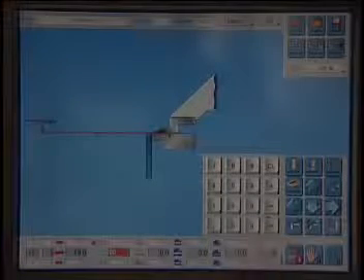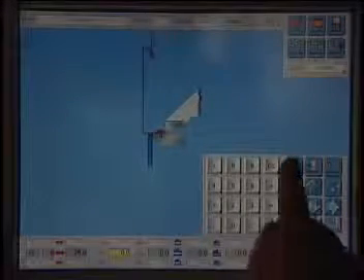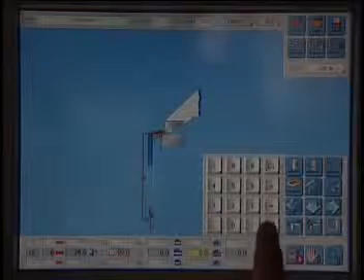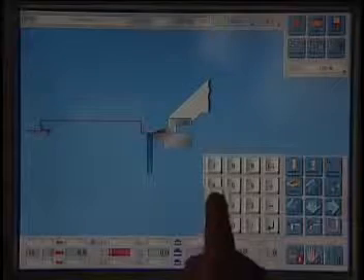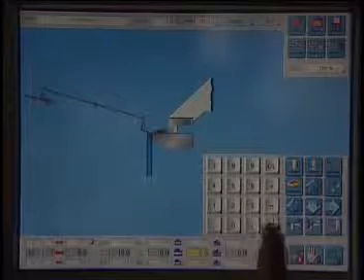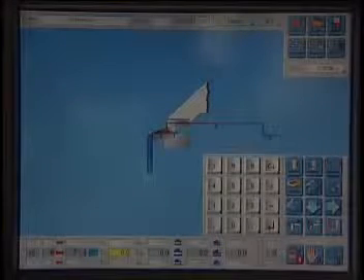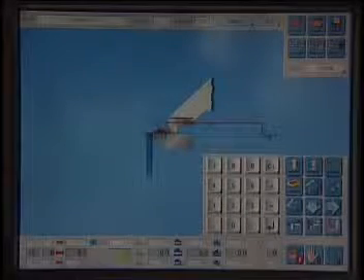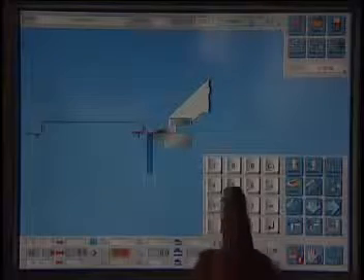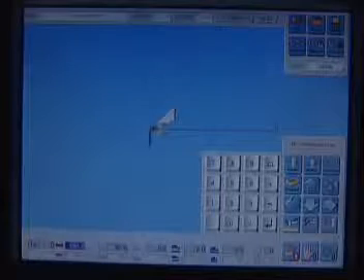Let's start with the opposite side. The logic is the same. Enter new backgauge value, turn your profile if needed, and enter bending angle. If the next bend is out of sequence, reclamp your profile to the next flange number, and the basic logic starts over again. When your program is ready, push the Automatic button and start bending your profile.